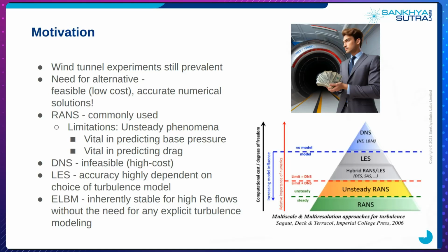The method that we make use of is known as the entropic Lattice-Boltzmann method. It's essentially inherently stable for high Reynolds number flows without the need for any explicit turbulence modeling, due to the reasons that I mentioned in previous slides.